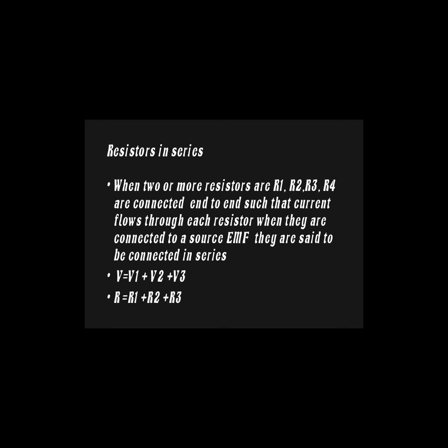The end of one resistor joins with the end of another resistor, such that current flows through each resistor when they are connected to a source, EMF. They are said to be connected in series. In series connection, they do not divide the current. The same current that flows through A flows through B, flows through C, flows through D, or any number of them.